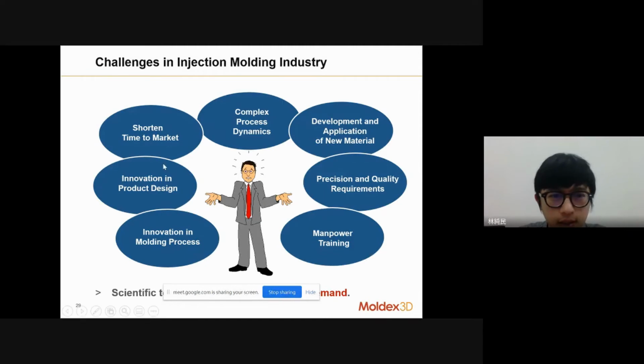And like I said, there are two things before we do the manufacture: not only the mold design but also the part design. The part design is similar to our product design. We need to think about there being no significant thickness changes. Otherwise, it will cause something like a weld line. So how to design the product is also very important, because if some position is too thin, it will also cause issues. So we need to think about this.